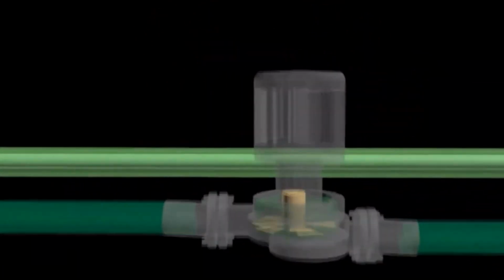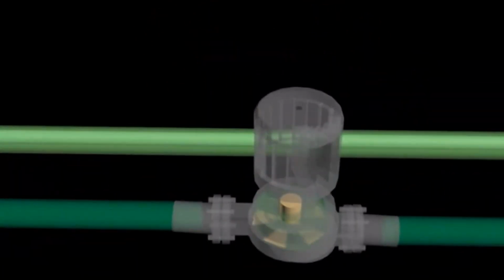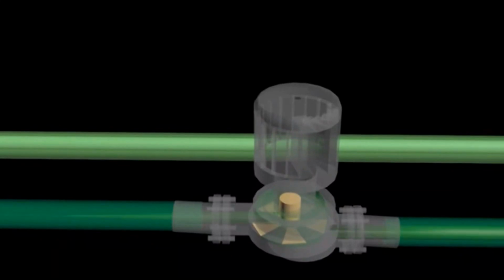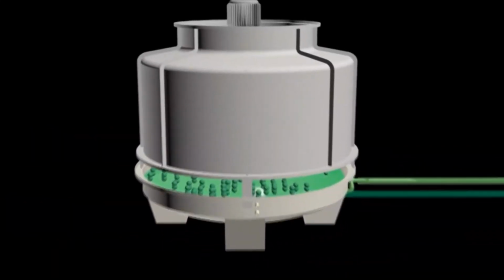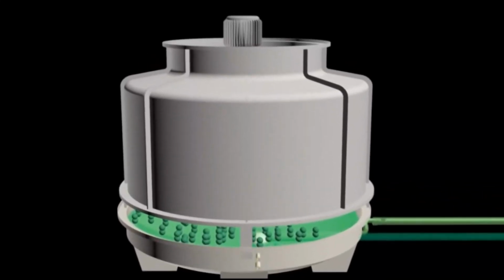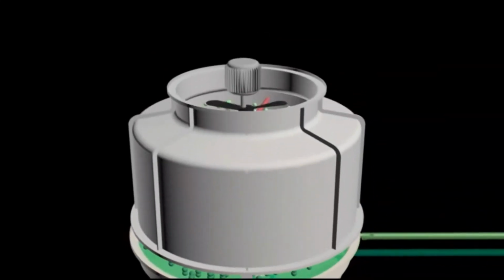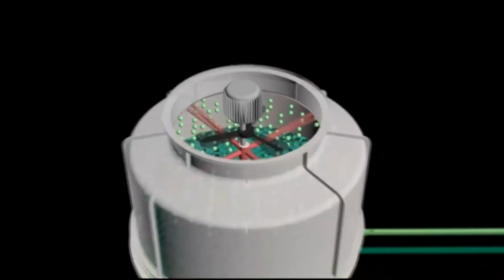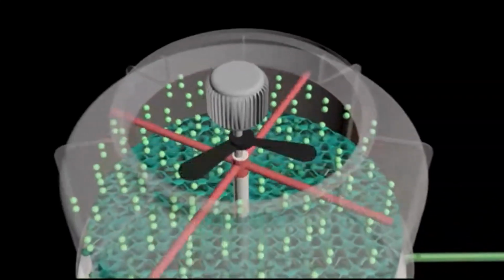From the condenser in the chiller, condenser water flows to the cooling tower with the help of centrifugal pumps. This water is called condenser water return. This condenser water will pass through the rotating sprinkler blades on the cooling tower. These rotating blades use pressure generated by the condenser water itself.